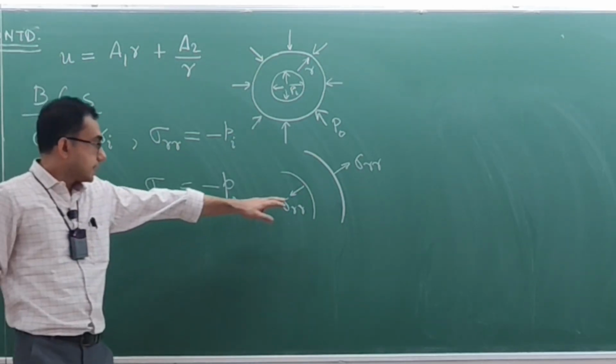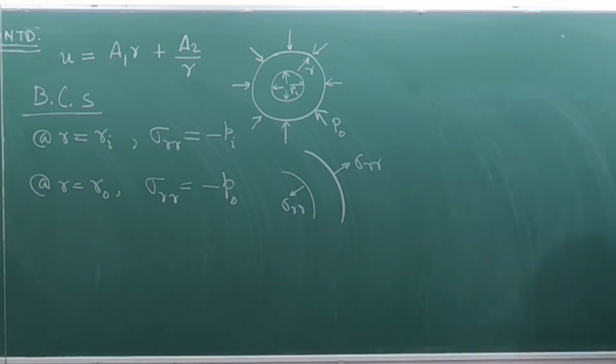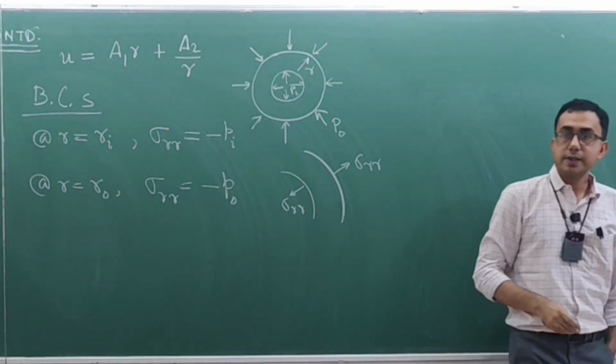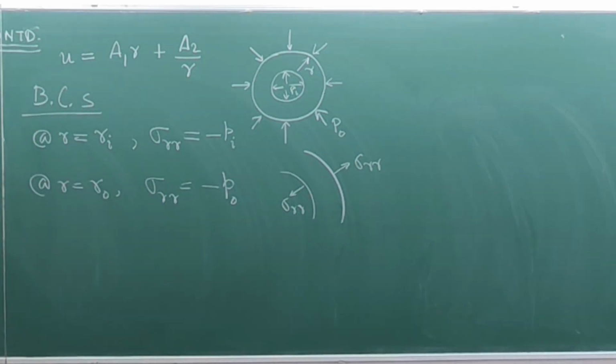If you're not sure what is happening here, always think in terms of that little stress element. Earlier we had seen these kinds of things, this stress element. So if you have your x-axis like this, your y-axis like this, do we not write this as sigma xx pointing out, and on this wall also sigma xx pointing out? So it is exactly in this fashion. Okay, nothing fancy.